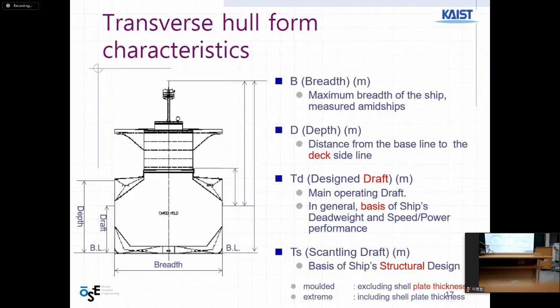Yes, draft is already explained to you. You need to embed this baseline, and there are two draft lines, right? Design draft and scantling draft. Very similar, a very small difference. Sometimes it's the same, but this one is based on structural design, and this is for cargo capacity and hydrostatic calculation, so deadweight calculation, speed and power. This is structural design.